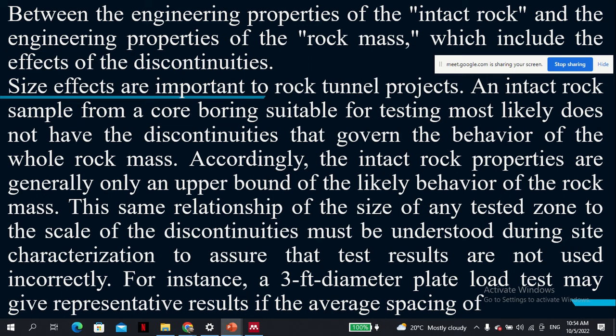What we are saying is, when you're sampling, the sampling may be very limited because you can only sample a limited diameter, and the properties of rock vary both vertically and horizontally. If you just take a limited diameter, you may not capture the discontinuities that appear horizontally, and even when you're sampling vertically, there's depth.